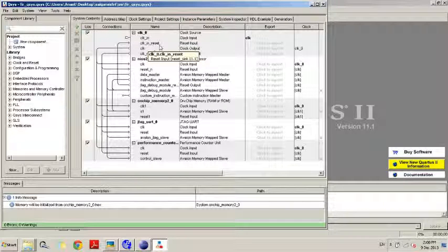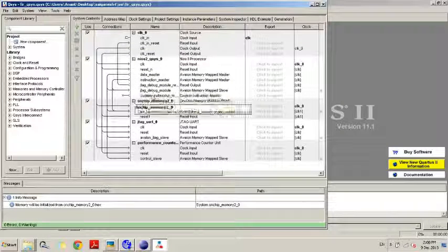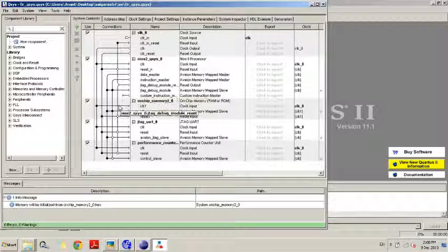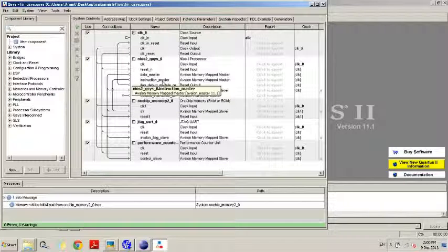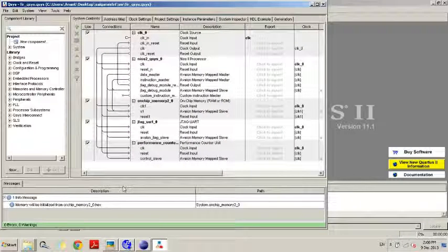All the clocks and resets have been connected properly. Clock and reset are provided only to the Nios 2 processor. Since on-chip memory gives instructions to the processor, it's connected to the processor. No other components are connected to the instruction master. Data master is connected from the processor to all the peripherals. There is an interrupt request from JTAG UART to the processor.